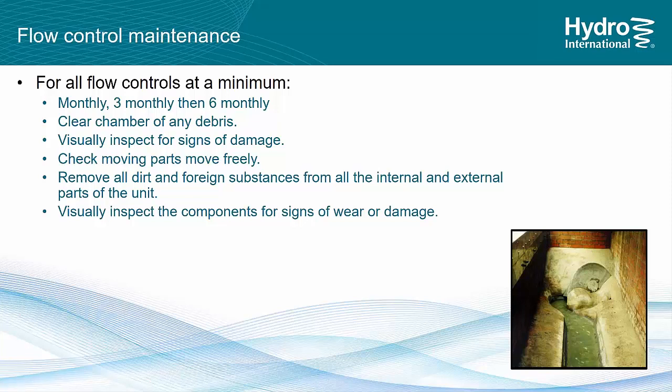And once the site is built, maintenance frequencies should be monthly to 3 monthly, then 6 monthly for the longer term. Chambers should always be clear of debris every time that you go and visit. You visually inspect for signs of damage and check moving parts, and remove dirt and foreign substances from the internal and external parts of the unit to make sure that those other bodies don't come and cause an incident.